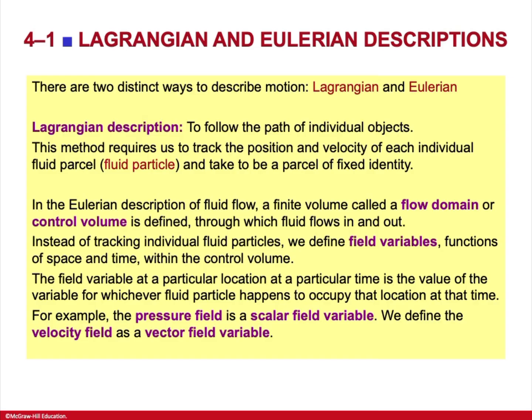And another way of describing objects is called the Eulerian description, which is more commonly used in fluids, where you don't necessarily follow each particle point by point. You observe the deformations or the changes at a given location, and at that location you might have a new particle coming in or moving out, because you're just observing at the same point.